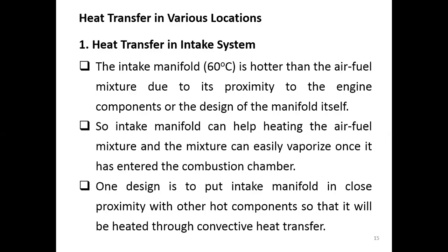So the intake manifold, due to its higher temperature, can help heat the air fuel mixture, so the mixture can be easily vaporized once it enters the combustion chamber. So here, we intend to have heat transfer from the intake manifold to the air fuel mixture, so it easily vaporizes and can mix well.